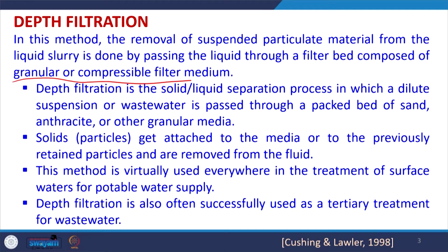Now, depth filtration is the solid liquid separation process in which a dilute suspension or wastewater is passed through a packed bed of sand, anthracite or other granular media. What this statement means is that we can have a combination of media also. It is possible to have a single media, dual media, or tri-media packed bed through which the wastewater is filtered.